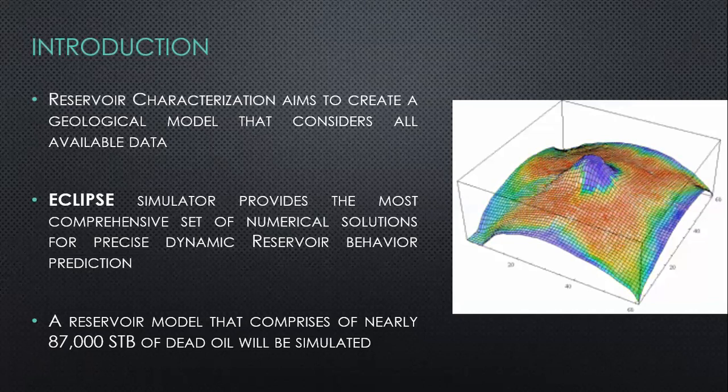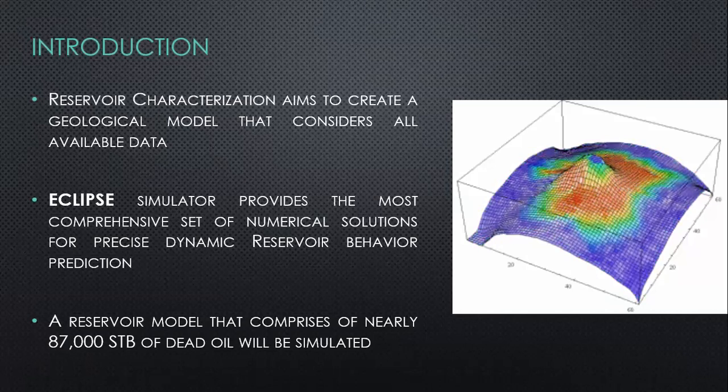Fortunately, Eclipse software has all those qualities, which allowed it to be the industry reference for reservoir simulation for over 25 years now. Using Eclipse, we will simulate a small reservoir comprised of 87,000 stock tank barrels of dead oil, which is known to be highly viscous, therefore very hard to produce. Then we will apply several recovery methods in an attempt to find the best one to recover the dead oil present in our reservoir.